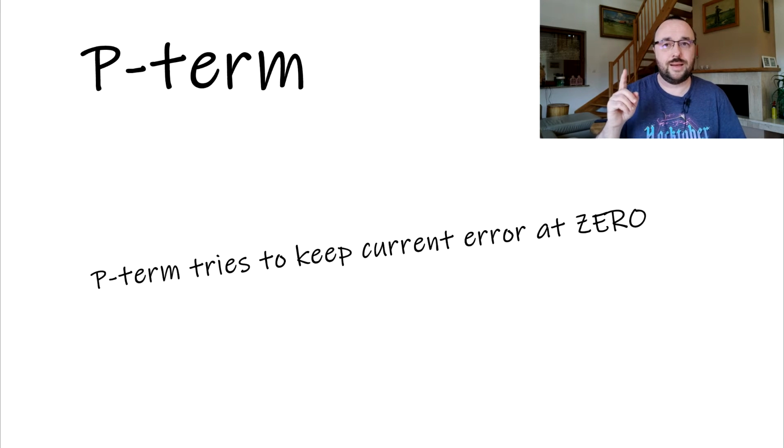Very important: with current modern multirotors, the oscillations from too much P are really hard to observe in level flight. You really have to push it to feel it, because we really improved quite a lot of things. Still, the rule applies. If the mechanical response is not able to track the error and keep it at 0, then probably the P gain is too low.